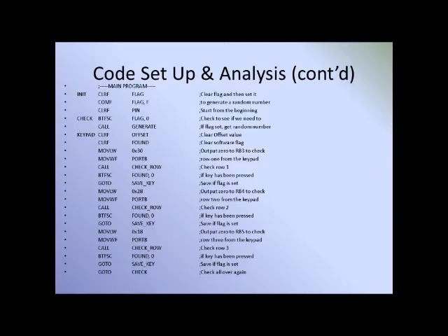In addition to the software flag for generating a random number, the address location 41 hex, which is the pin equate, was used to keep track of which number in the 4-digit sequence the program was at. Its relevance and use will be noted later on as well. After bit testing the first software flag and generating a random number if necessary, the program went on to check whether or not a key was pressed on the keypad.